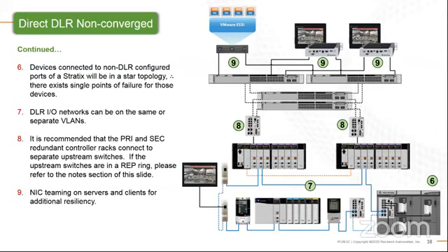Typically inside of the motor control centers, we would have one switch dedicated for multiple pieces of equipment. So at that level, that would still be a star design, but as you leave the Intelligent Motor Control Center, whether it's to redundant controllers or simplex controllers, we have ways of either doing that via redundant star, device level ring, or potentially even parallel redundancy at that level if we needed to.